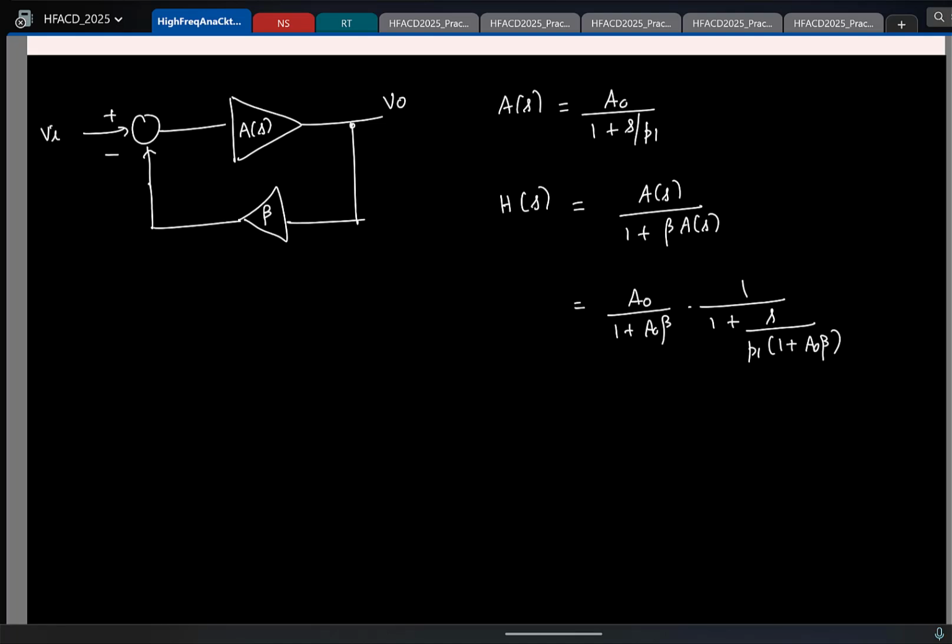So now how will you decide if this transfer function is stable or not? If I give you a transfer function like this and ask if this is stable or not, what is the ultimate check? Poles should be? The pole should be in the left half of S plane. So here, do you think the pole is in the left half of S plane?